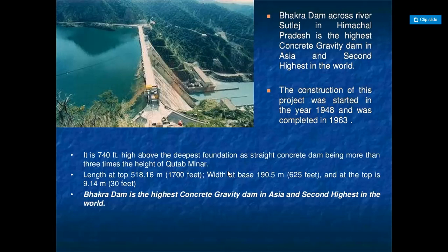Seiche effect, H7, due to reservoir setup or undulation in the reservoir water. A seiche is a big wave with a wavelength as big as the container, in this case, the reservoir. Weight of the dam, V1, vertical water loading, V2, uplift pressure, V3, and seismic force, V4, which is the force acting on the dam in the vertical plane.